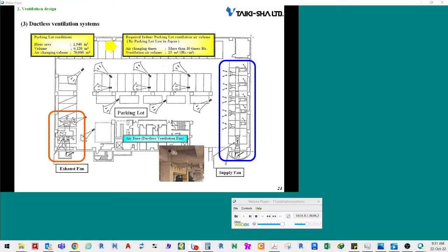Induced ventilation systems may be used for large spaces. If so, intermediate ducts are removed. Required apparatuses are locally positioned at the required positions. As the air is blown at a high speed, neighboring air is induced and sent. As a result, the overall ventilation efficiency is higher. In the drawing on the slide, one example of the induced ventilation systems is shown.